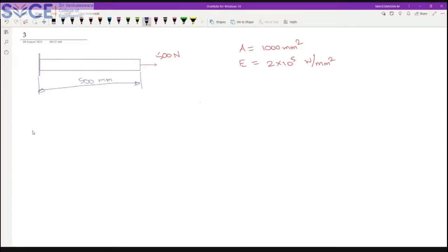So you can see that it's axial loading which is acting like this. So how do you solve this by using strength of materials? We have a common formula. We have del L. So we understand del L is equal to PL by AE. This is the formula we usually use, right? Where P is the force, L is the length of the bar, A is the cross-section area, and E is your Young's modulus. So if I substitute, I will identify the total change in length, right?